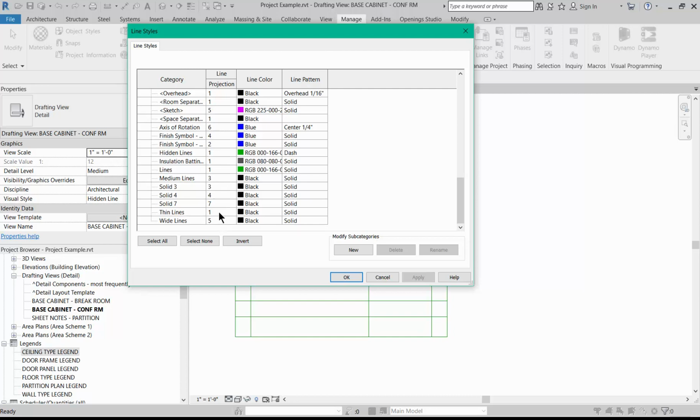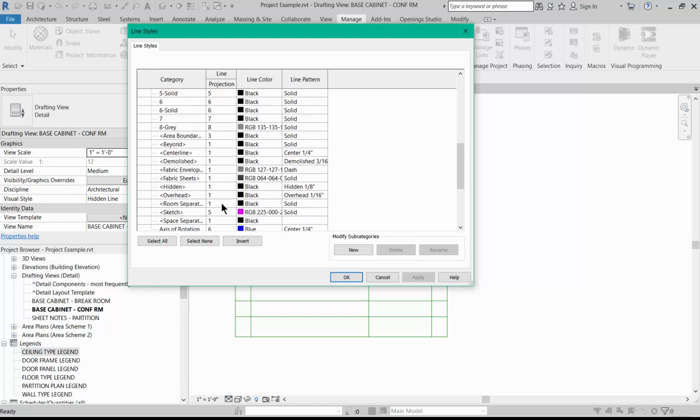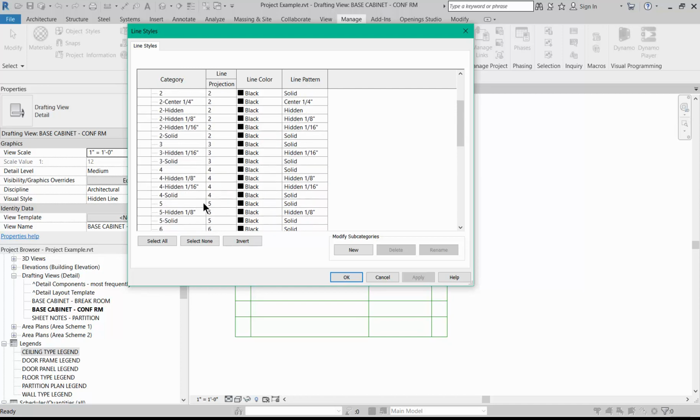But then between 1 and 3 you do want to have a line that's a 2, and you probably want to have a 4. So you probably want to have the range as shown here between 1 to 5, and have options on the different dashes, so the hidden line or whatever, and the scale will dictate if we are actually going to see the dash depending on the scale of the view. So just keep that in mind.